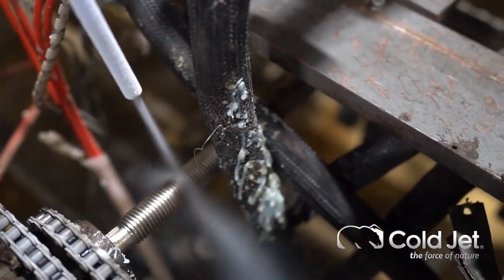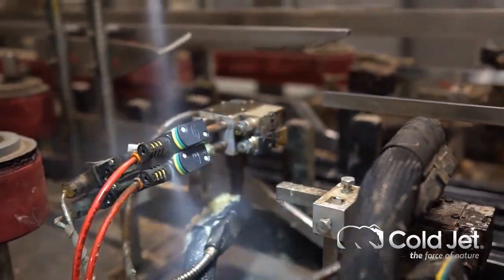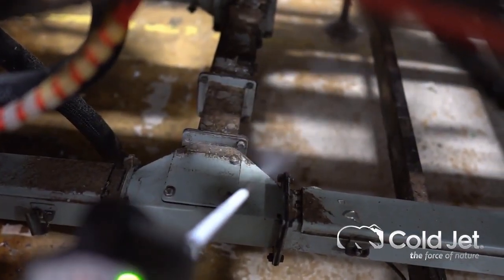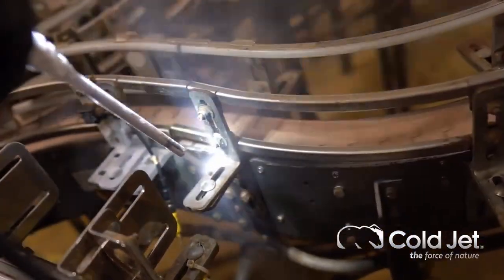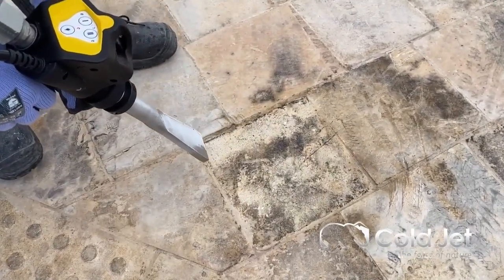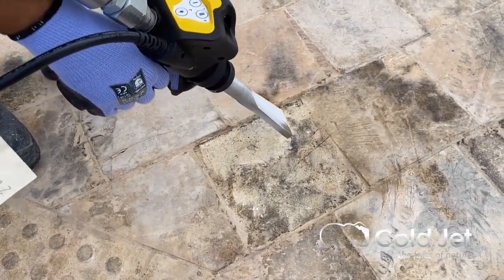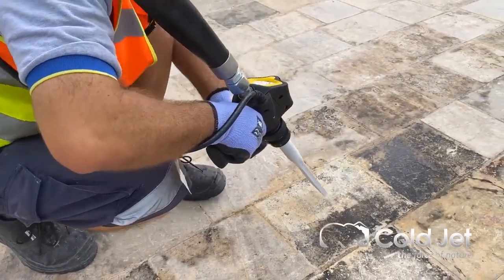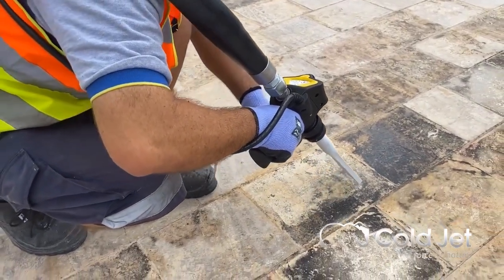The second part is the thermal shock or the cold. Dry ice is very cold at negative 109 degrees Fahrenheit. So as it impacts that surface, it chills whatever contaminant you have on there and helps to release the bond that it has on that surface. And then lastly is the sublimation part. That dry ice, as it hits and transitions from that solid state to the gas state, it expands to 800 times its size in order to pop off that newly released coating. So to kind of summarize that down a little bit, we use the acronym ICE, I for impact, C for cold, and E for expansion or sublimation.